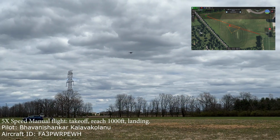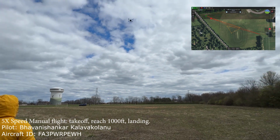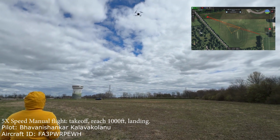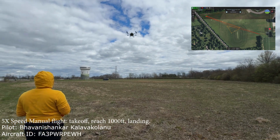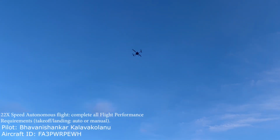The payload system of the drone employs a vertical drop parachute system which utilizes a 2-arm spring-loaded lever system to ensure accurate, consistent deployment of the payloads. Throughout the design, verification, and testing, it was concluded that this deployment system can consistently and accurately drop water bottles on the designated target.